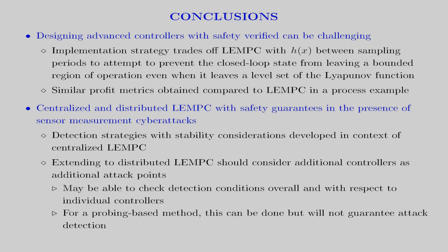Methods explored for centralized LEMPC could be explored in the context of a distributed framework. A probing-based strategy could allow for detection conditions to be checked overall and with respect to individual controllers. However, the probing-based method does not guarantee attack detection.